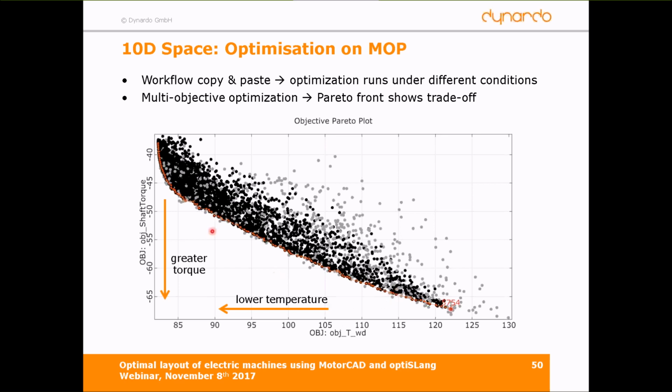With a limit of 50 for the torque, we get 90 degrees. If we want 65, well, with this implemented constant cooling setup, you have to accept 115 or 120 as the resulting temperature from the increased losses. So you can run lots of single objective optimizers, or you can run here a couple thousand designs on the meta model.